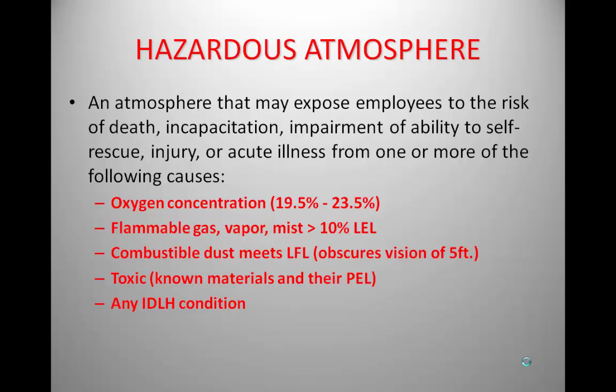They go on lunch break, they cut their acetylene off, they think they cut their oxygen off, they go on lunch, they come back in an hour, get inside their space, so their oxygen bottle has run out into the space, they get their striker, go to ignite their torch again, and there's a possibility of an explosion. So that's an example of a mechanically induced oxygen enriched atmosphere.